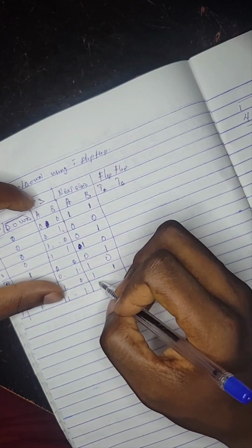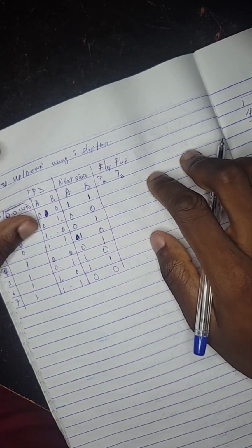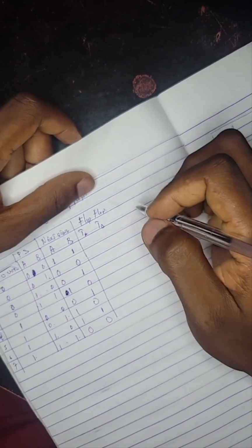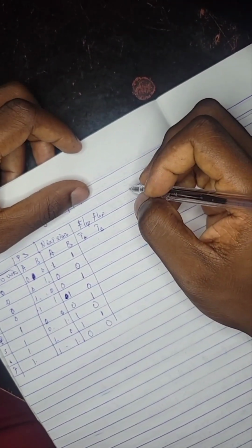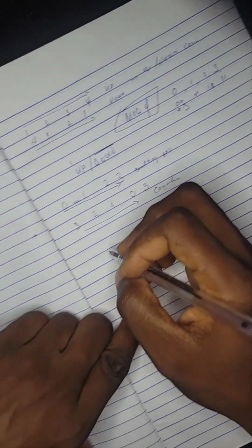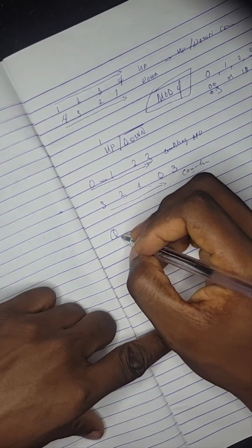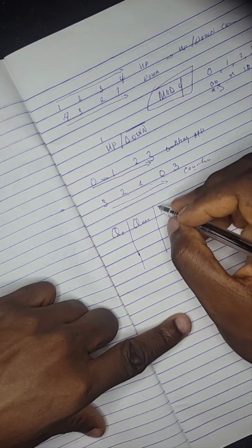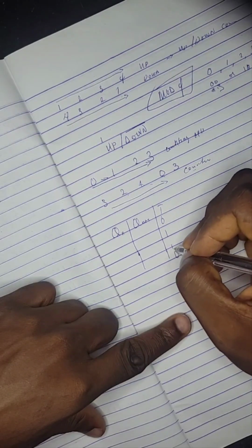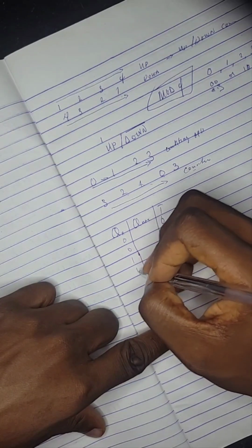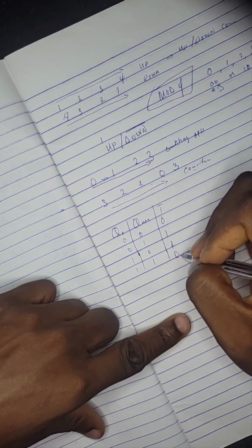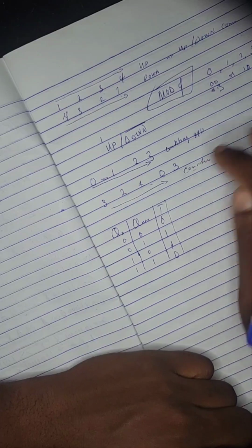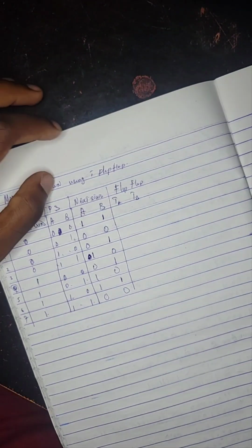When you're on 3, the next state is 0. Now the next thing for you to do is the flip-flop. To do the flip-flop, we have to make use of the excitation table. The excitation table for the T flip-flop is Qn, Qn+1 and T, which is 0 1 1 0, 0 0 1 1, 0 1 0 1. So 0 1 1 0. And we have this. Now we have to look at it here.